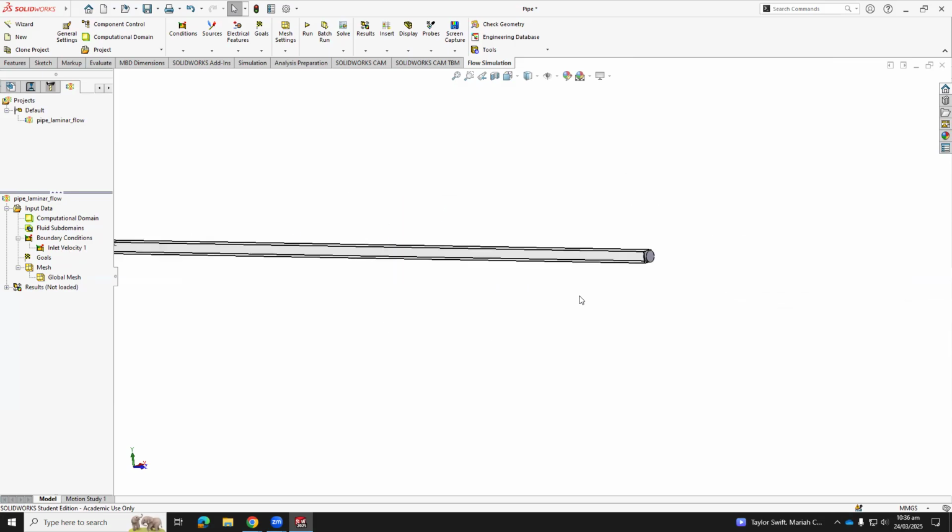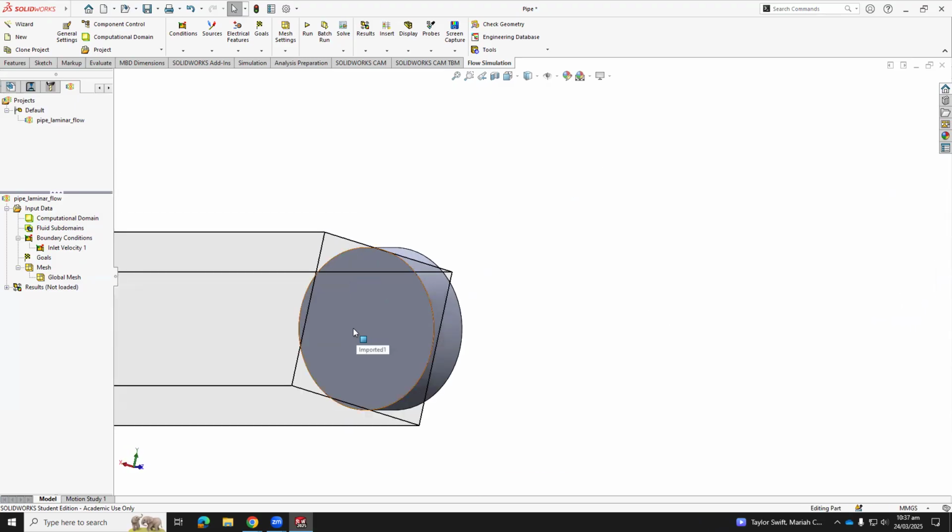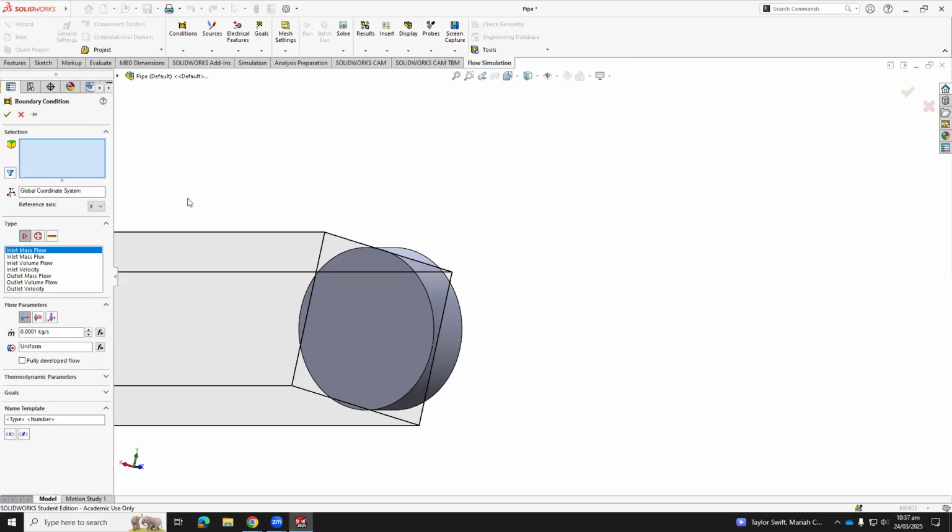Now I zoom out by scrolling the middle to go to the other one. This is the other one. Nothing is selected there. I go again, right click on boundary conditions, insert boundary conditions. By nature, we always use the following. At the inlet, we use inlet velocity or volume flow rate or mass flow rate, three options. At the outlet, we use pressure. Because it's open, how is the pressure? We go in that middle one, pressure opening. It means a pipe is open at the end. So water comes out like a hose for the garden.